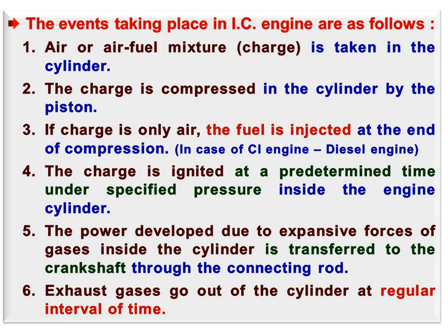At that time, fuel is injected in an atomized way inside the cylinder. The fuel is injected at a predetermined time under specific pressure inside the engine, when the piston reaches top dead center during the compression stroke.